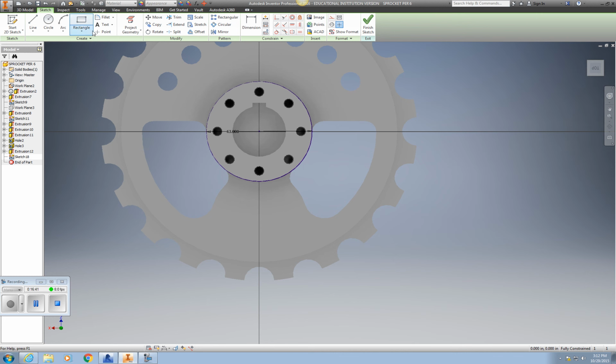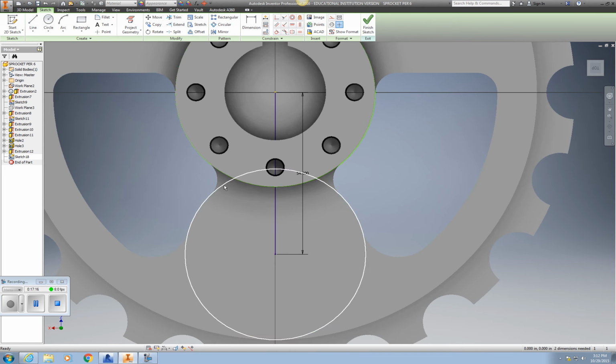Now I also need to put in that 54, but let's delete the dimension. And I need to place a vertical line from the center coming down at 54 once again. Escape. And I'm putting in a diameter of 57 again. Enter. Hit escape, delete.